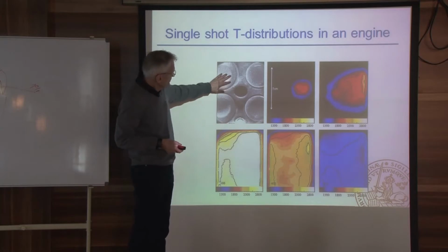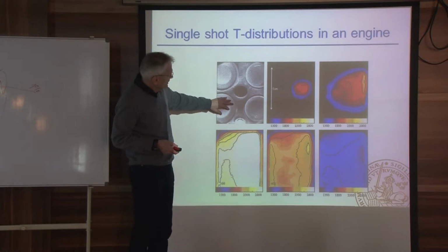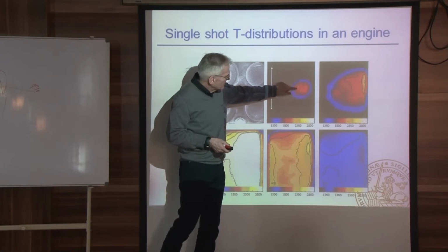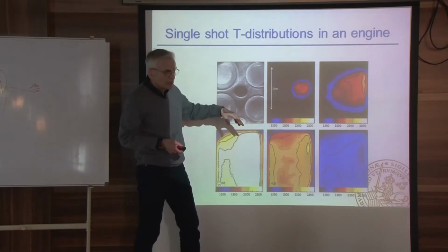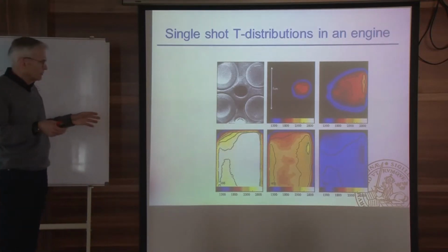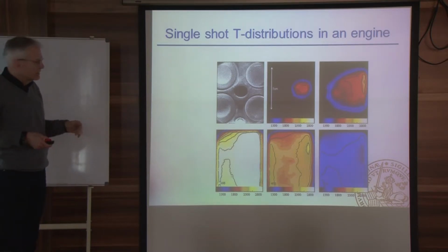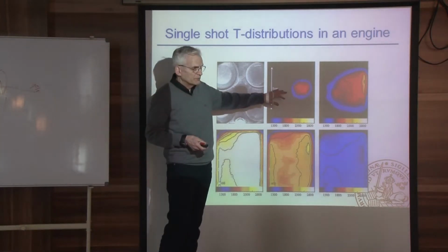This is what the detector will see without any combustion going on. And here we can see how the flame is ignited, and now it's in temperature instead, as a function of different crank angle degrees. There we just take advantage of how the population is on the different rotational and vibrational levels. So what might have seemed very, very academic before the break is now actually converted into a real temperature.